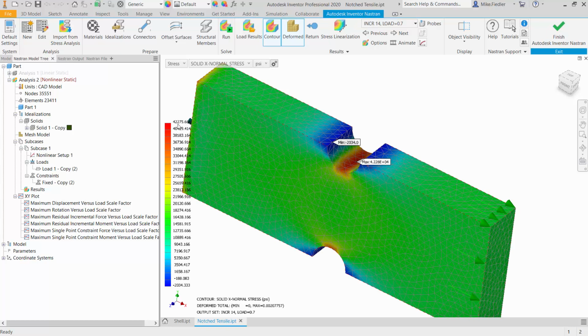So there you see our change in the stress is only 2,275, and that's a function of the tangent modulus, right? The slope is not as steep as the Young's modulus, so for the same increase of load on the model, the stresses are going to increase a little bit less than they do in the linear range. So you could certainly interrogate the results that way.